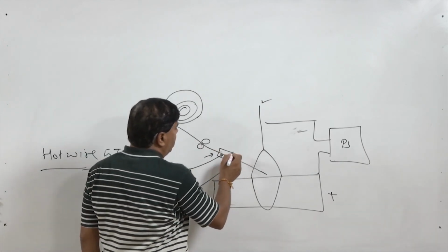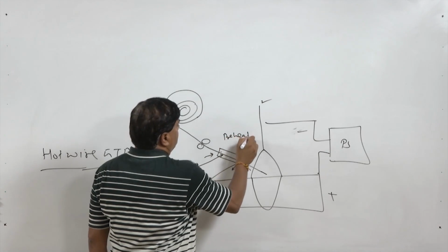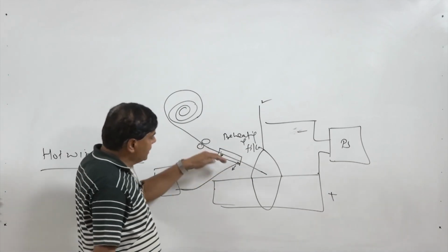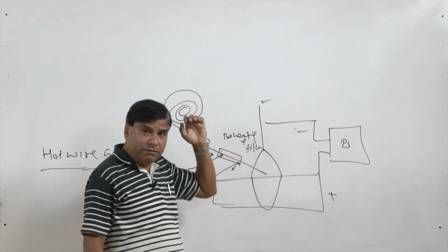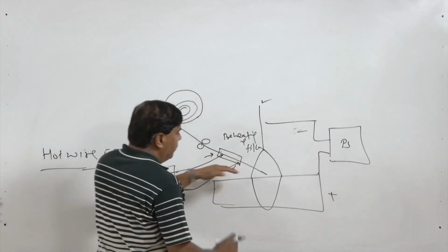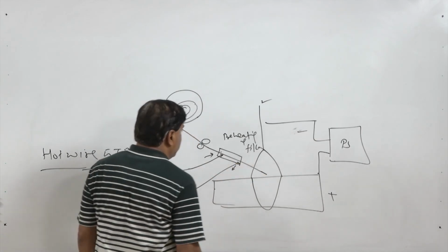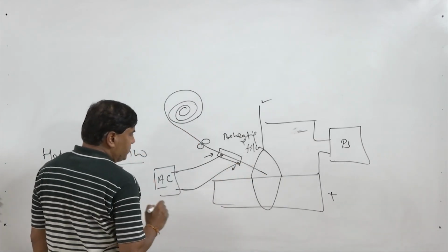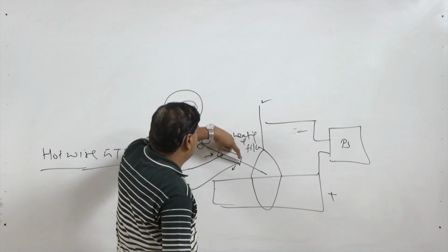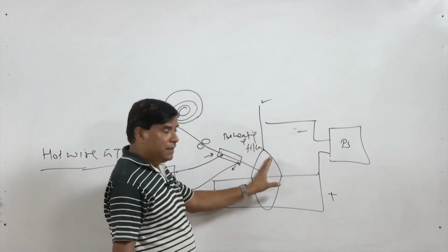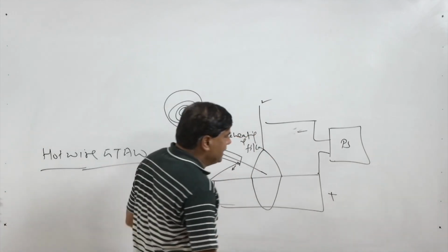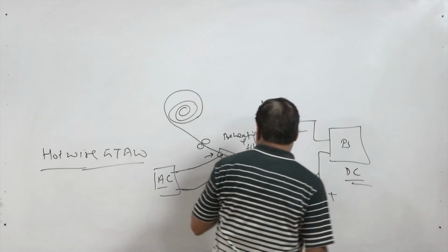So, in this zone basically the preheating of the filler takes place. Preheating of the filler will increase the temperature of the filler before getting into the arc zone. So, this process actually reduces the amount of heat required during the melting. For the preheating purpose AC is used, so that whenever there is current flow through the filler, it does not interfere with the arc or the welding current, which is generally DC in the case of the gas tungsten arc welding process.